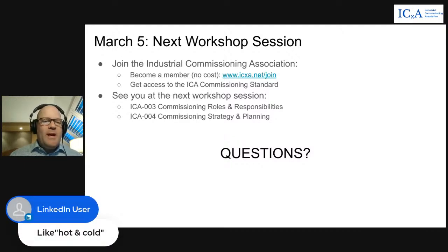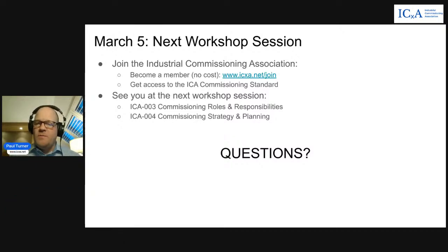What about terms like hot and cold, dry and wet commissioning? Those may be useful terms, but I've never found them to be too helpful on projects, so we've actually retired some of that terminology as well. When you look in the document, hot, cold, dry, and wet aren't specific stages that we've defined in the commissioning process. There's confusion between working on an electrical system or a mechanical system. Usually you don't want to do wet commissioning of your control and protection systems. Water and electricity don't mix too well, so we've just dropped all those terms to avoid that confusion.